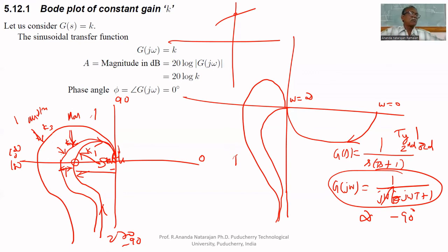The output magnitude will increase, that's why the plot will amplify like this. But it becomes unstable, because it crosses 180 after -1. So by using this frequency response, we can say that this much k is required to become unstable. That is called gain margin.